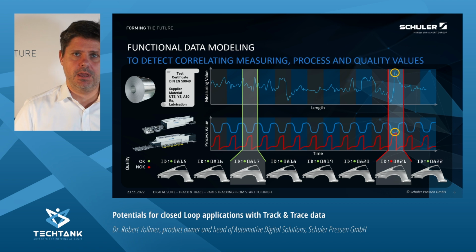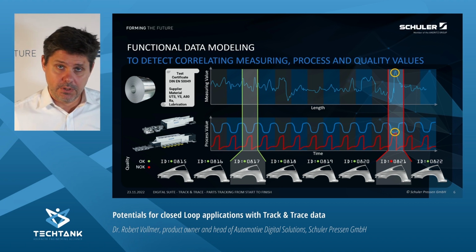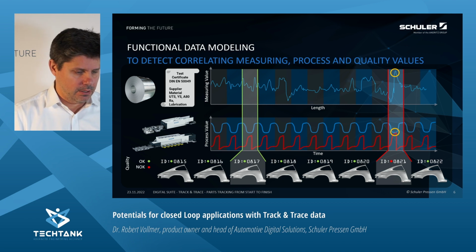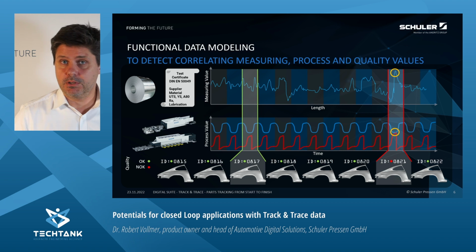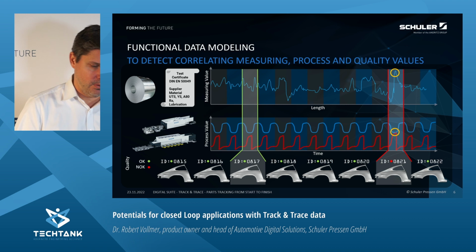You also get tolerances and specifications within which this material should be. Afterwards, we can do an additional measurement in the coil line, integrating measurement technology on the basis of length. We also cut this model into pieces, because this is what you do in reality: you cut blanks out of this coil and map this data to the single blank.